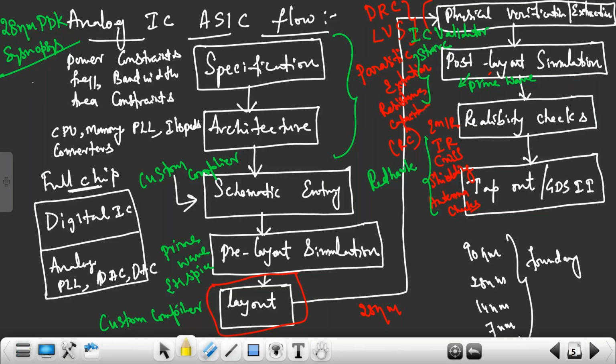In the Cadence tool for 28 nm we'll be using MOSFET. From Cadence we'll also work with 18 nanometer. This is FinFET. It is not a planar MOSFET, it is a FinFET. In Cadence, the tool for schematic capture is the Virtuoso tool. And to do pre-layout simulation, the tool is called Spectre, the Spectre Excel tool.